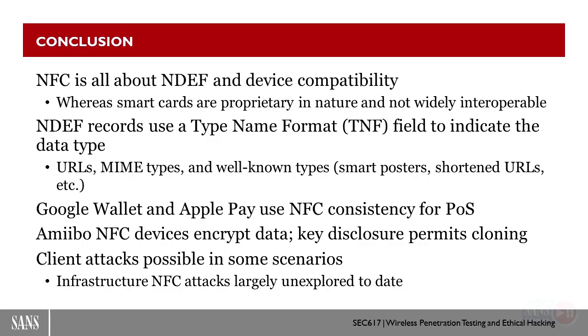We use a type name format to indicate the data type, with some of the well-known types for additional shortcuts, telling the devices how to process the data and potentially with which applications. We talked about Google Wallet and Apple Pay, in which they use NFC and properly formatted NDEF data for exchange of payment information, regardless of where the secure element is actually stored.